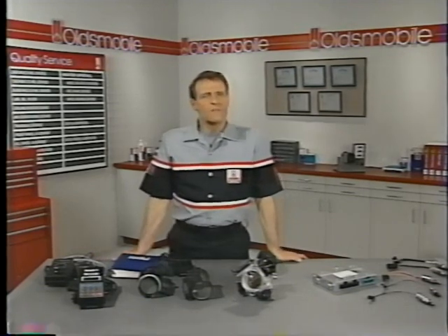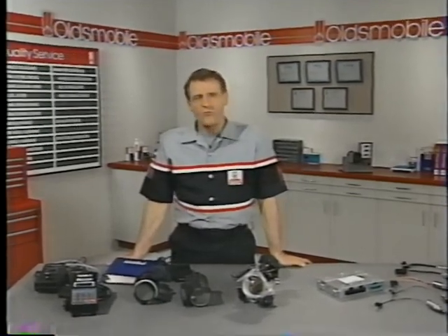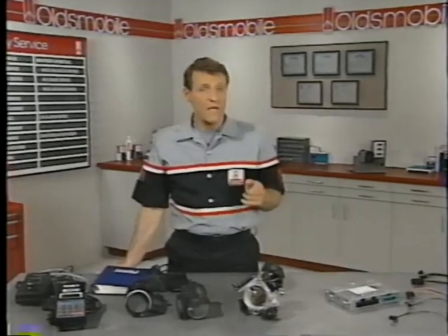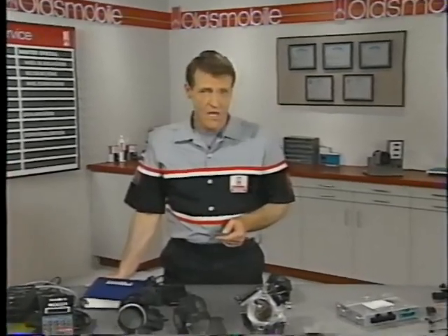Finally, problems in the intake system can create drivability problems that may appear to be MAF sensor malfunctions. Possibilities include an air cleaner obstruction, a leaking or blocked vacuum line, or a buildup of residue on the throttle plate. So don't forget to check these items if you want to fix them right the first time.